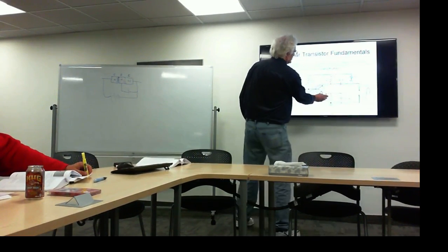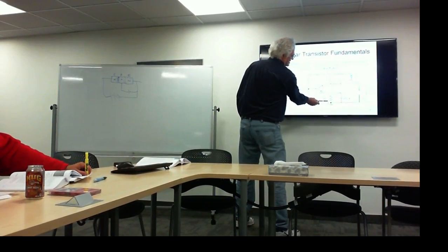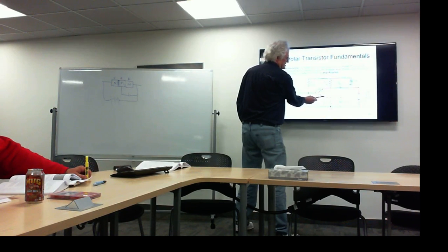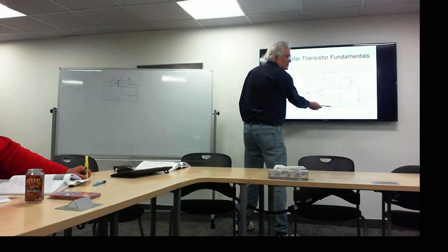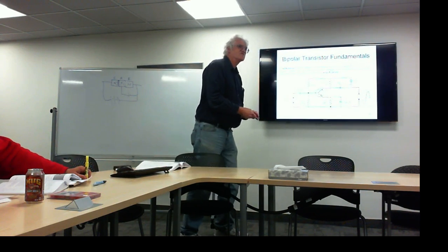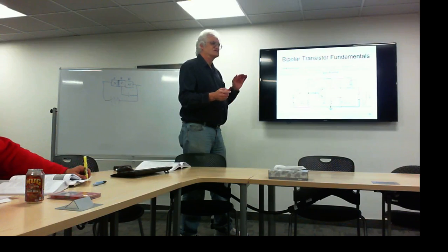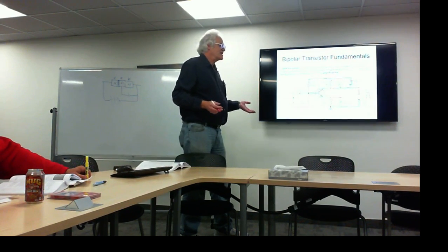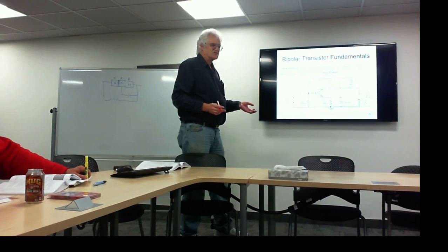Actually, no. What you're showing here is the fact that you've got a resistor in series with the emitter, so the emitter is going to be sitting at 1.9 volts above ground right here. There are no real absolutes. Generally it's not so much an absolute positive or absolute negative. It's always talked about with respect to something.